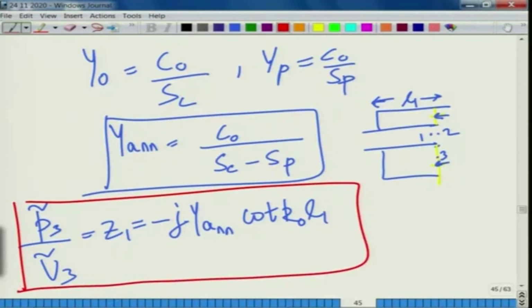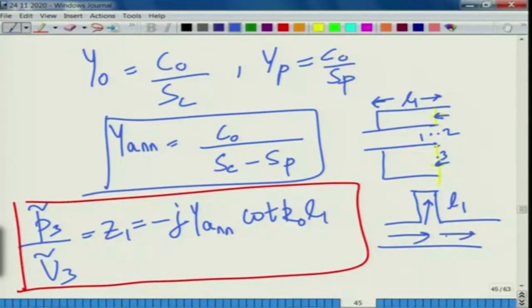So, remember, if you recall our last lectures, if we had a certain tube such that it was closed at one end and there was a wave coming here. So, if you could tune the length L1 such that most of the acoustic power is diverted in the side branch and very little or negligible power is transmitted downstream, then you can significantly abate or control the noise or the sound that is propagated downstream, at least in those frequencies or for tonal frequencies.